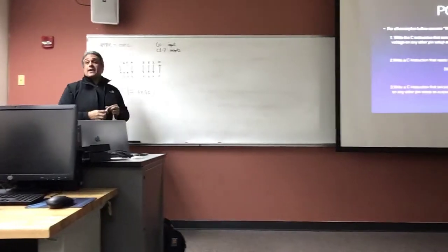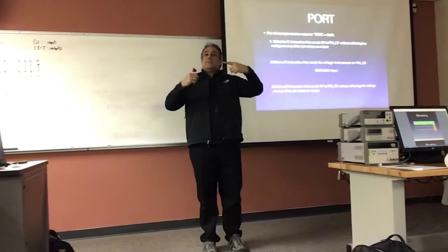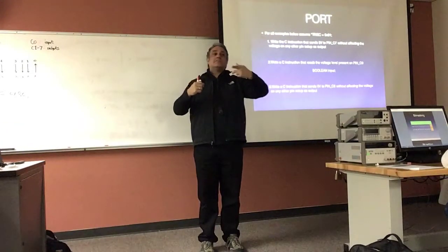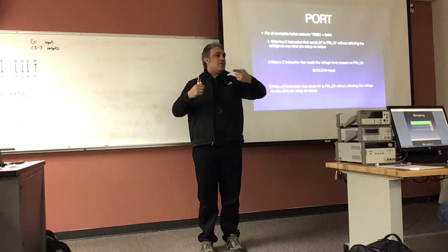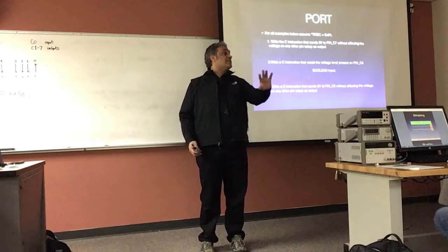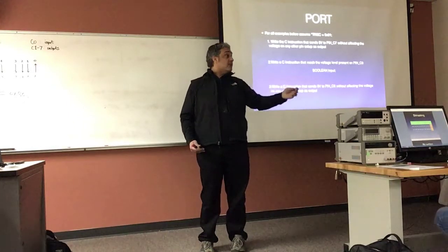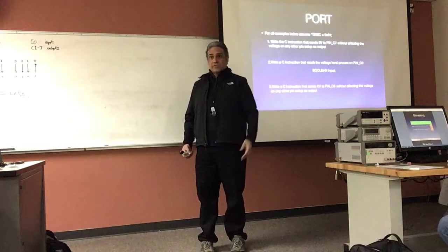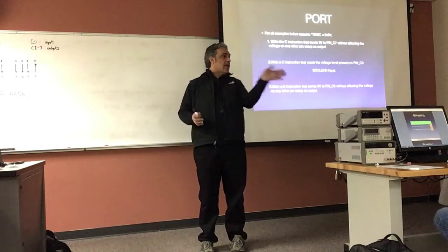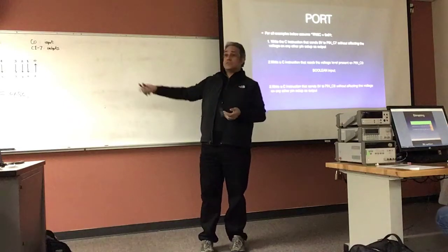The number one mistake that I tend to see in exams is we tend to miss the difference between a tri-state behavior and a port behavior. Sometimes I ask, can you put 5 volts on the output? And then we use the tri-state to do so. The tri-state can't put 5 volts out. The tri-state can only do input versus output. That's all it can do. It can just handle the direction. But if you want to drive voltages, you got to use a different circuit.